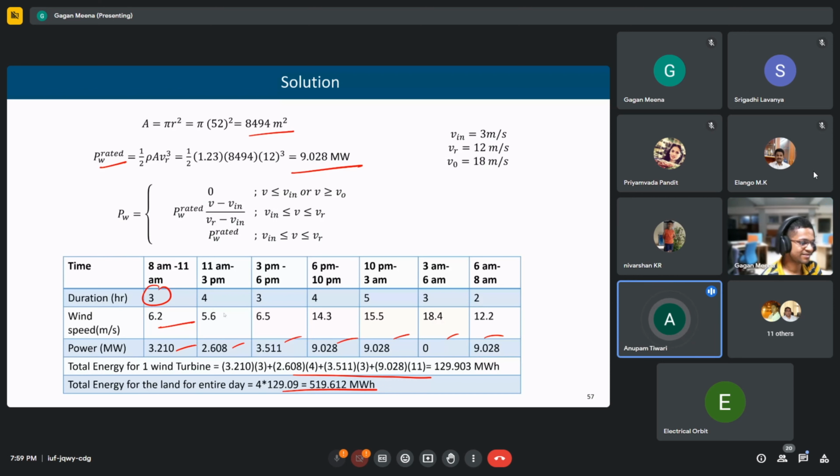That is why these turbines are not in use, in which the pitch angle is changing? No, they are being used, right? Pitch angle control is being done. For extracting maximum power, we have to do pitch control. They have servo motors inside, for each of the blades.